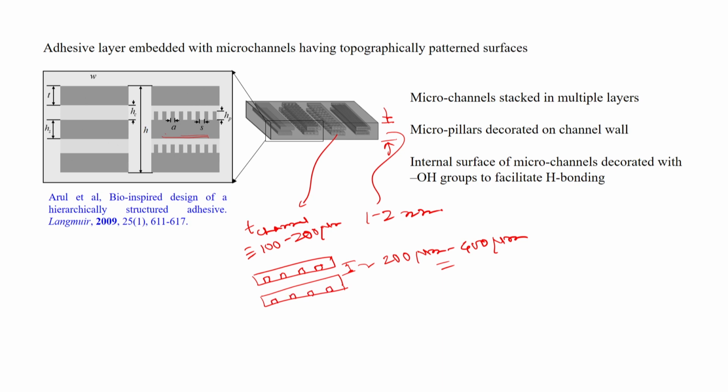So, we would like to take advantage of self adhesion hysteresis. That means this surface will come in contact with this particular channel, the top surface of these pillars, but also this contact area splitting. So, contact area splitting and self adhesion hysteresis, both effects can work together. So, that is the idea of designing these adhesives.